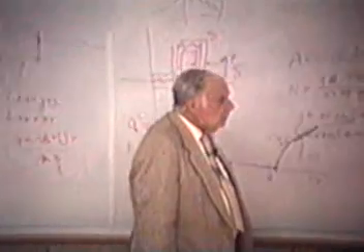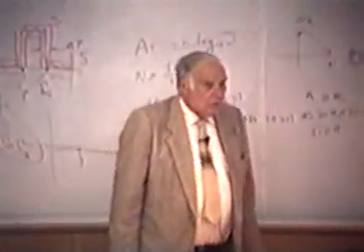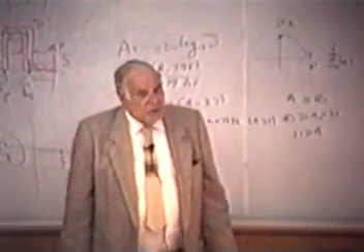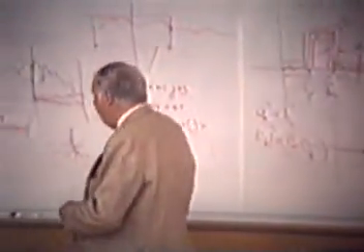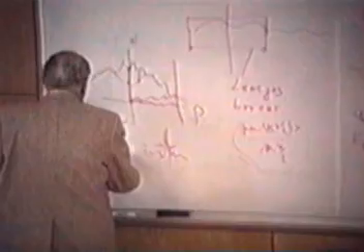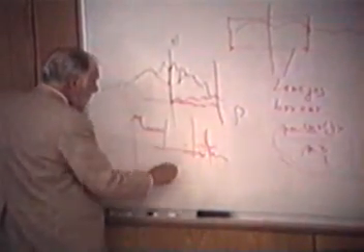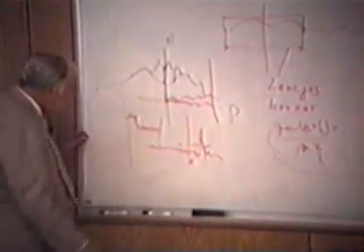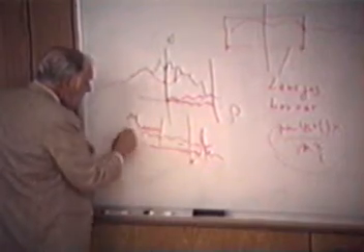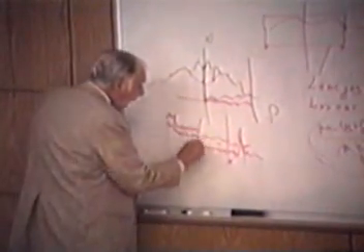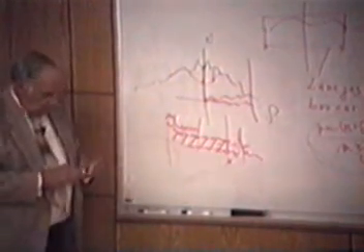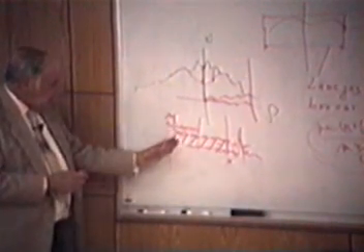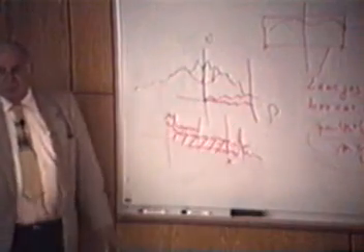Even if you want only low frequency signal, what one often does is oversample. If I oversample much more than I have here, then the folding frequency, say, would be twice as far out. The signal is now like this. I can remove more of the noise if I oversample, and then use a low frequency filter to cut off this and remove all that noise.